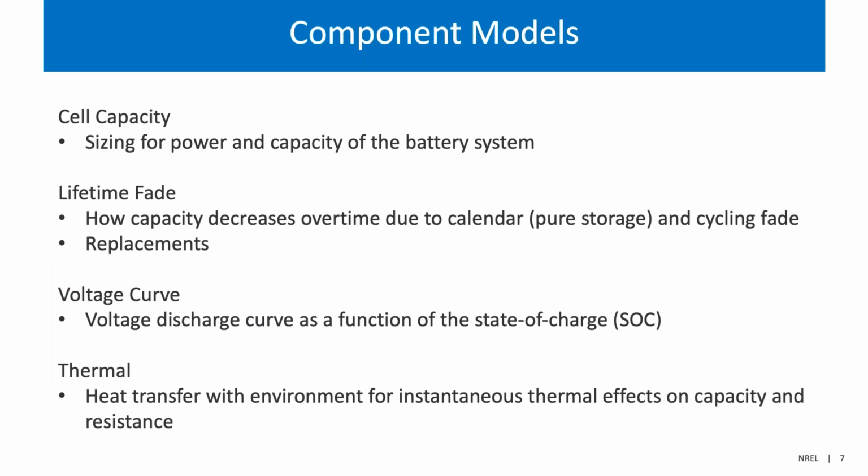So similar to how the detailed PV model is based on modules strung together in series and parallel to form the system, the battery model starts with a single cell and its characteristics such as nominal capacity and voltage. These are used to build up a battery system with some power and capacity. The efficiency losses due to racking, hardware for monitoring, controls, and safety get swept up into a power converter section and charge limit section.